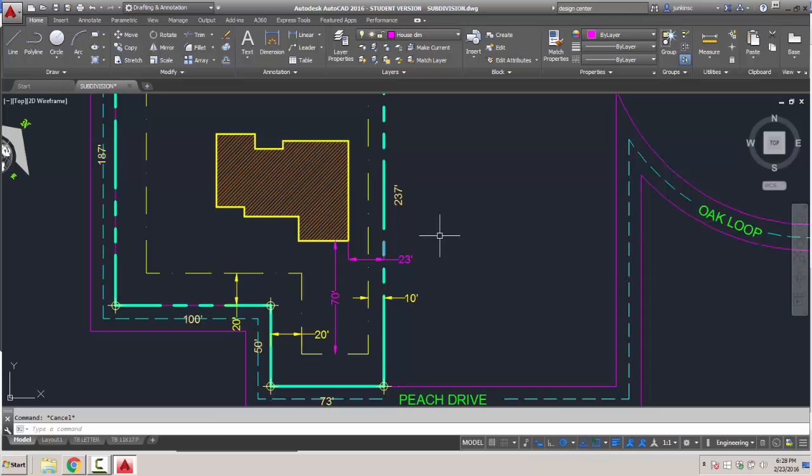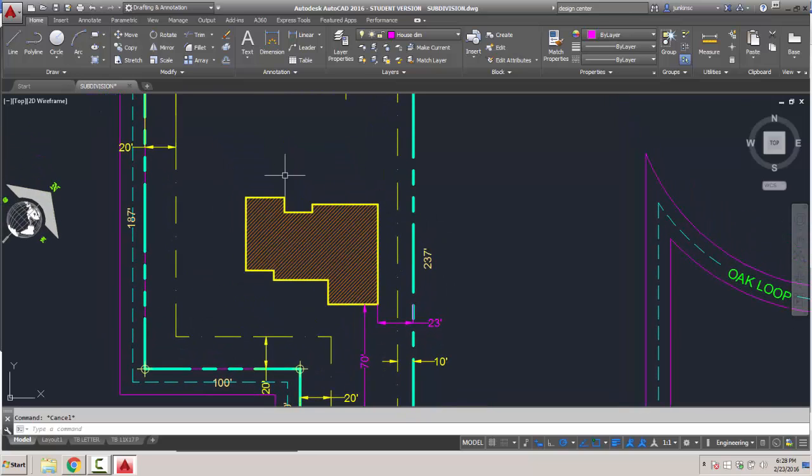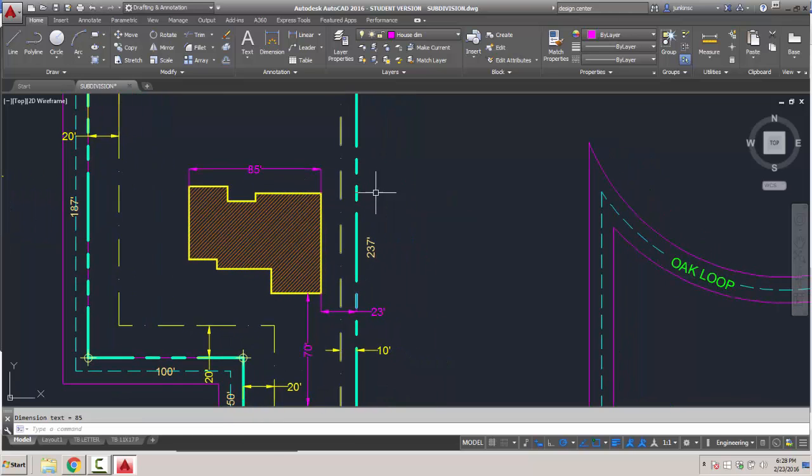And then we've got the overall building dimensions, overall meaning end to end. So what the outermost points of the building are going to be. This should be 89 feet. Of course, mine's 85, so they got some additional stuff on their drawing. And the overall length they have is 66. Mine's 62, so they use a little bit bigger footprint. And it probably, you know what it is? It's the roof overhang.